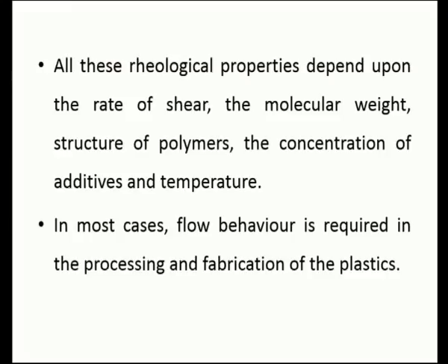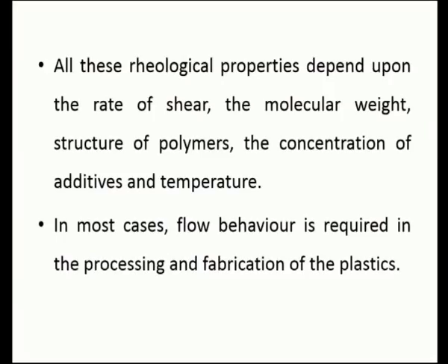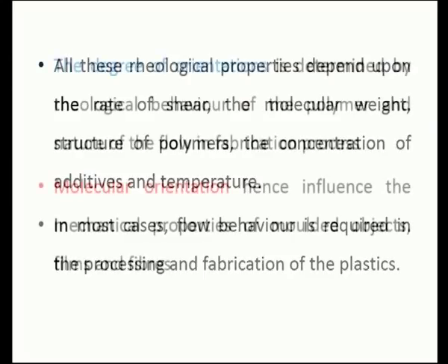All these rheological properties do depend, as I told already, on the shear rate. We will see what is meant by the shear rate, how the viscous liquids are getting sheared inside a processing machine. Of course, the molecular weight is more important, the structure of polymers, whether it has bulky groups present as a side chain, and then of course the concentration of additives. Additives here refers to all the coloring agents, pigments for aesthetic appearance, and the flow behavior is required in the processing and fabrication of plastics, and degree of orientation.